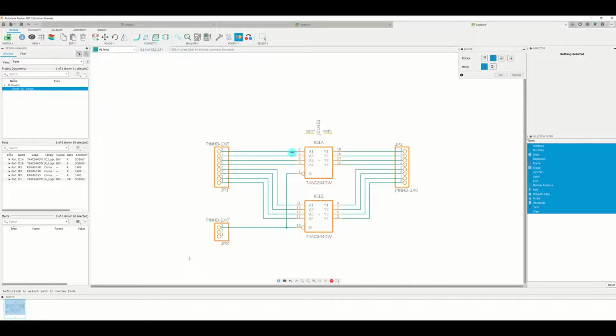Okay, so what I do is, for short lines, I just connect the lines, but for longer lines, meaning let's say one component is here and the other component is far away, and you have to pass through a lot of other wires, it's better that you just draw a short line or short net connecting the pins, and then label that pin, and then on the other side you just draw a short line and then label the pin, and the two will be connected. We can do that later.